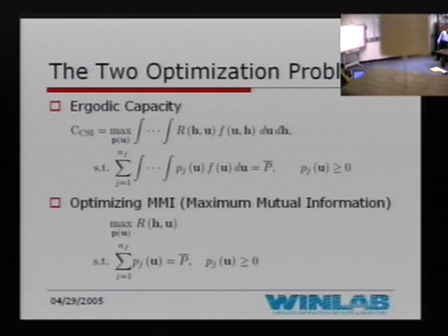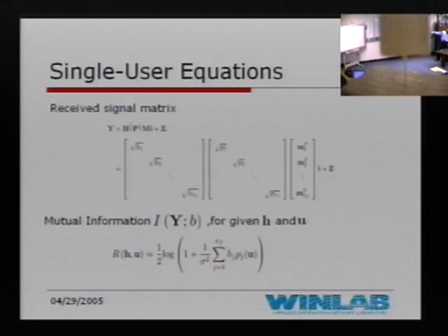It's basically over frequency. If you remember, I said the channel is constant for a block of NT symbols. For such a block of NT symbols at some time instant, the different frequencies have gains H1 to H of NF. What is NF? NF is the number of subcarriers. Remember, each row of this matrix corresponds to a subcarrier.